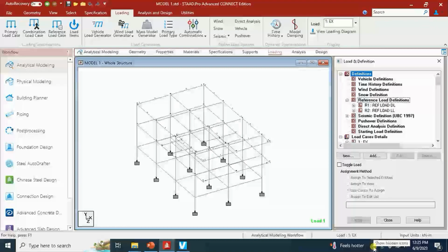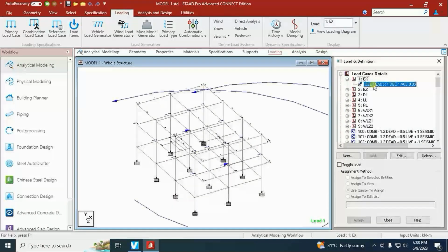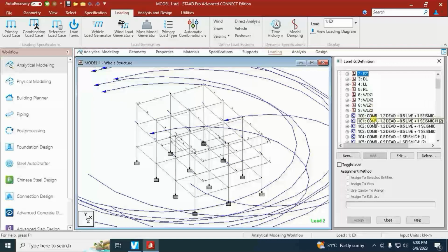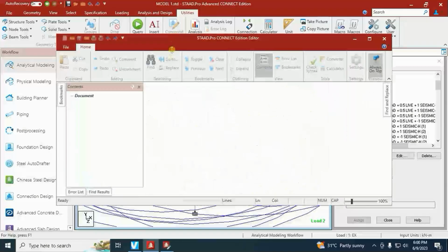Another thing is about the load combinations considering plus 30% of the orthogonal direction. Many of us encountered this error. Load command line is too long and will be truncated. Basically, load combinations with 30% additional taken from the orthogonal direction is employed only to seismic loads. Let's say we want to apply all seismic load combinations an additional of 30% from orthogonal direction. To do this, we just simply edit all the seismic load combinations in the STAAD editor.